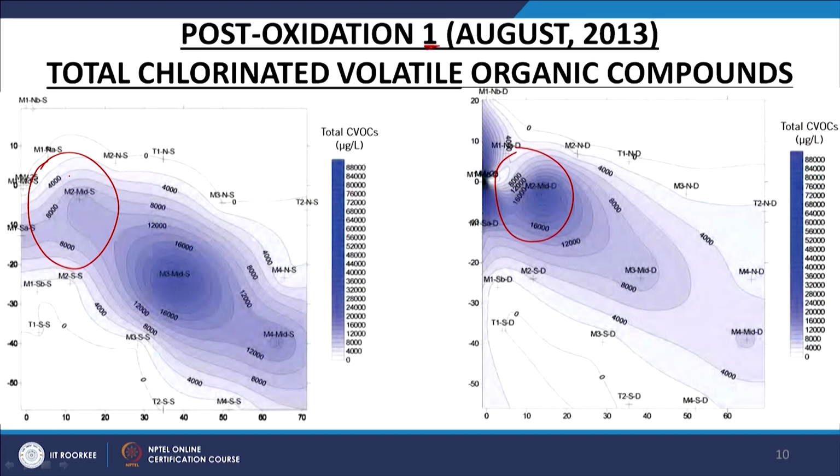And also if you remember, they waited for around 2 months or so before they monitored the relevant data. As in, if I injected the permanganate into the soil or groundwater today, only after 1.5 months or 2 months did the relevant people monitor the site. Why is that? Why not look immediately at how much time permanganate will take to oxidize these compounds? Because the reactions are going to occur typically in the aqueous phase, and now the contaminant in the water has been consumed, or has been oxidized.